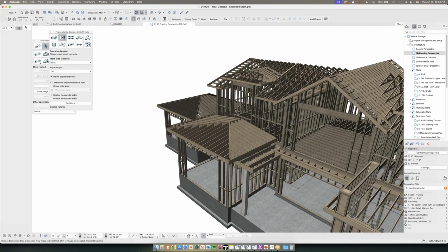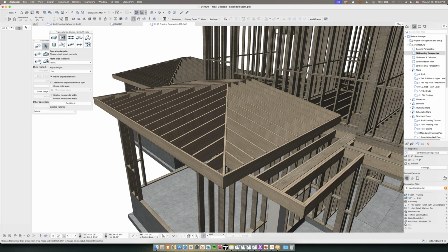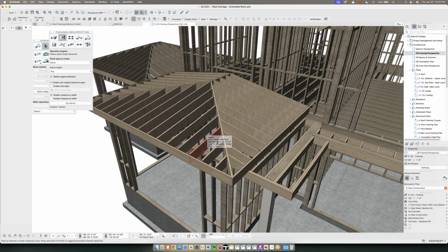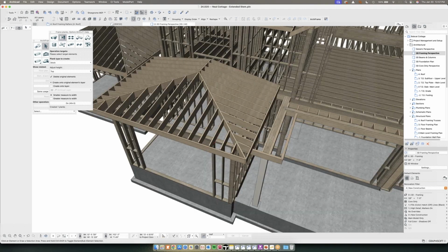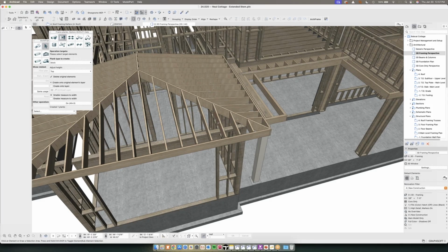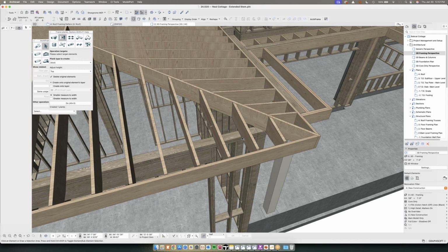I've just downloaded the Simpson hangers from Simpson's website in a Revit format, and just use Model Port to create them as an object in Archicad, and then I just implement them in Archicad. For example, here I actually put in the VAF2 rafter hangers, or the VAB2 rafter hangers, and the HUC 210 or whatever it is rafter hangers on the skewed one here as well.